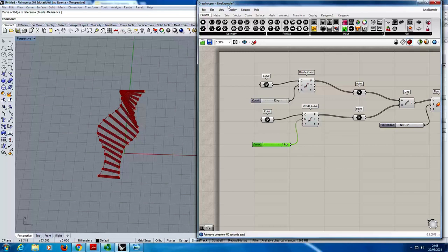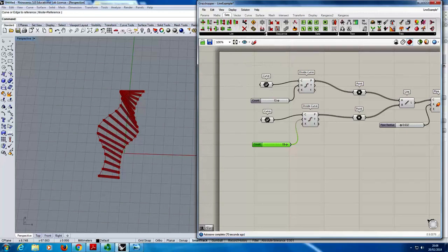Back in the good old days, there was actually an option on different components that would tell it to do that, but nowadays they've taken that out. So we can't do that anymore, but we can get that same behavior using this component here. This is on the Sets tab in the List group. It's called Shortest List.